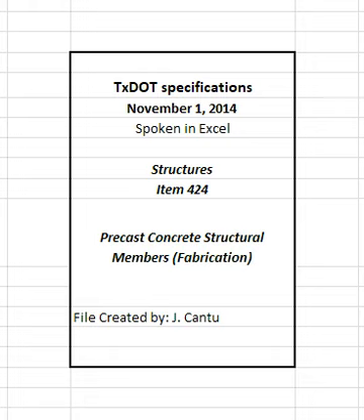4.2.7.1.1 Wet mat method. Use water-saturated cotton mats, burlap polyethylene sheeting, or other approved moisture-retaining materials. Anchor the wet mats adequately to provide continuous contact with exposed concrete surfaces. 4.2.7.1.2 Water spray method.